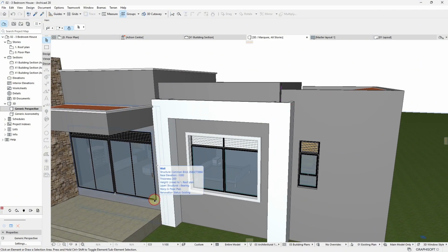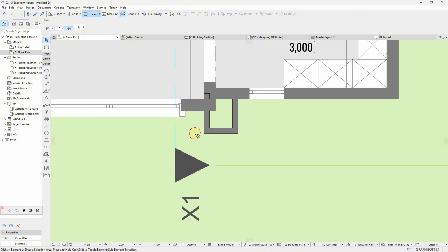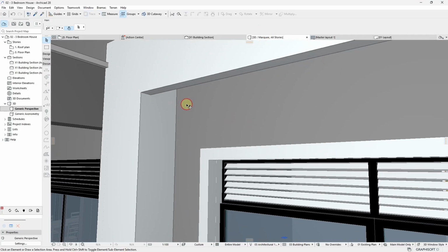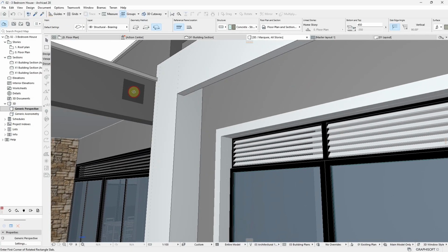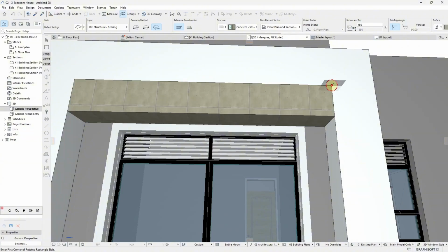And when you're doing this, make sure that it is as cheap as possible. That's why I propose using small blocks of 100 millimeters thick, so you don't need to do something so big. And then we shall also do something like a slab underneath to cover up that space. But all in all, you need to make sure that you can actually build it if you were asked to do it as the owner. So before you design anything on a building, know ways of doing it, and also know ways of explaining to people how to build it.